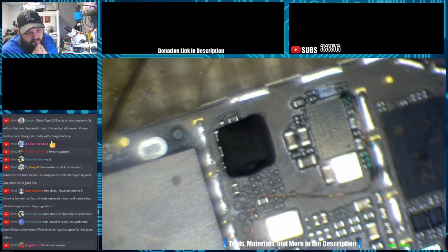I've got one here that I've been working on. I don't even know where it's drawing the power from, but with battery drain you kind of have to look for secondary symptoms. In the past, I've had battery drain issues where pieces of metal have gotten down inside of FPCs from where you're turning the screws. Some of the thread metal will come out and get inside the FPC. I had one where the home button was acting weird, like the fingerprint scanner wouldn't work, and I was like, why the hell is it doing that?